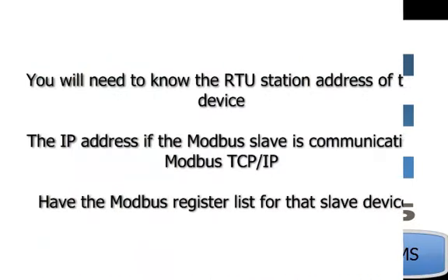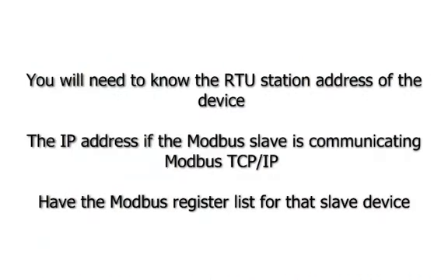Getting started, you will need to know the RTU station address of that device, the IP address if the Modbus slave is communicating Modbus TCP over IP, and have the Modbus register list handy for that slave device.